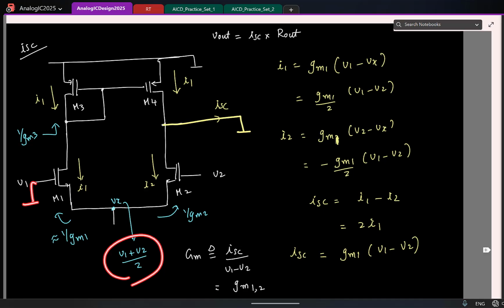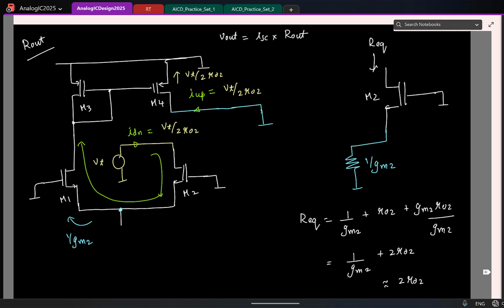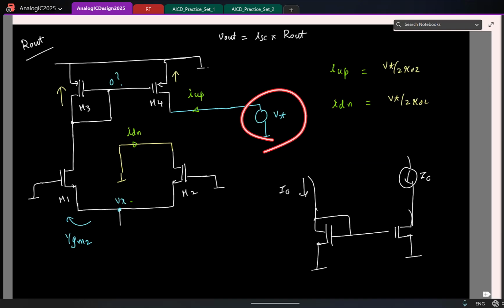Now in my experiment, I made V1, V2 0. So can I make this claim? I cannot, because I have removed V1, V2, but in addition I have introduced a third voltage source, a new excitation V-test. Maybe that can contribute something here. Not clear, but at least this argument is correct.